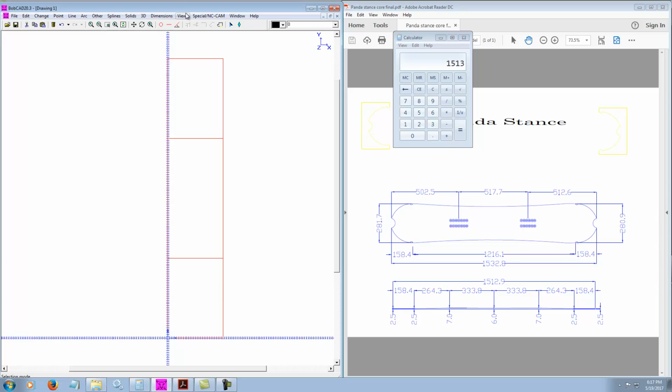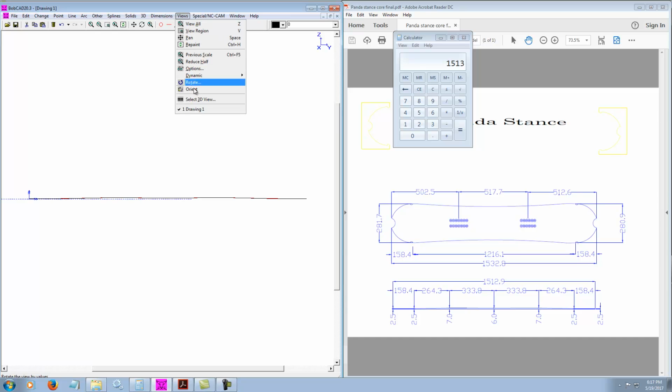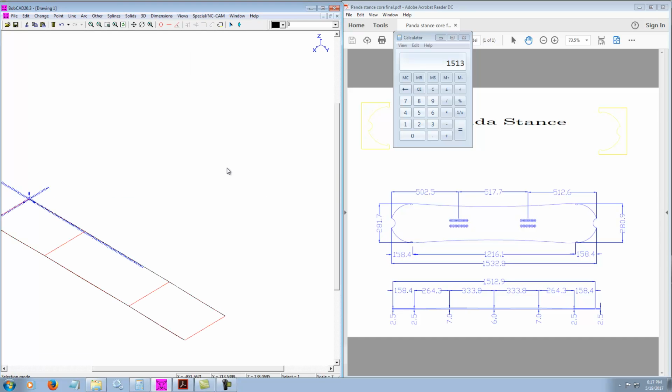Now, if we go to the side view here, view, select side, right side again, and we hit the Z key, you can see where I've got it highlighted, it has a 3-dimensional surface. Or if you go to view, there's an isometric view, which is a better way to look at the surface. It's sort of an isometric 3-dimensional view that shows you've got the surface.